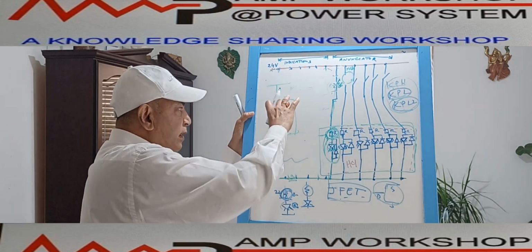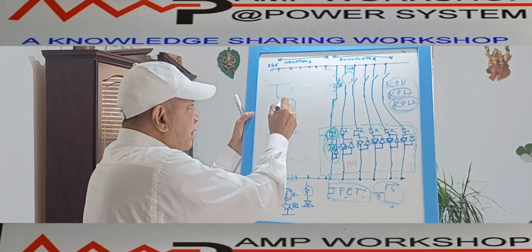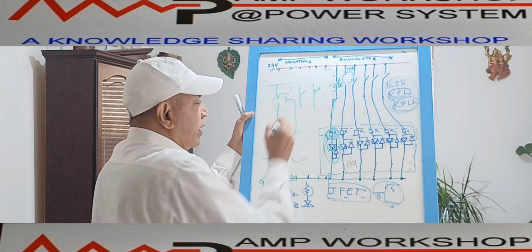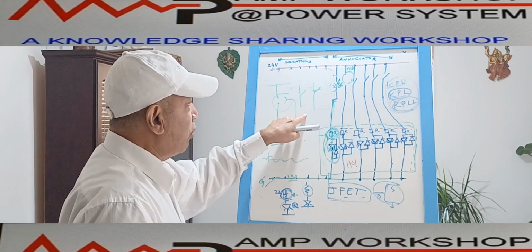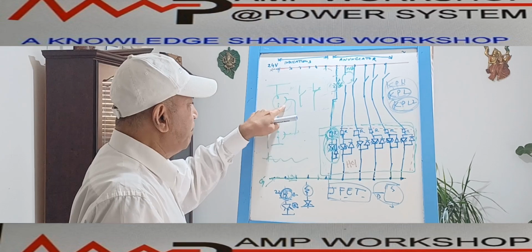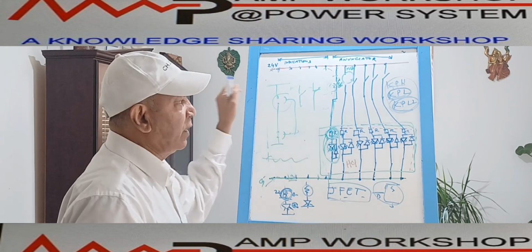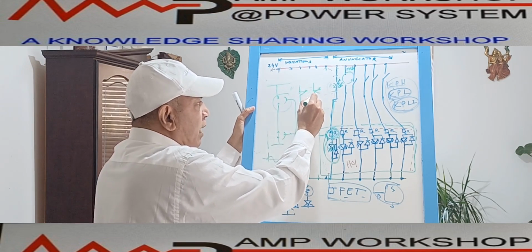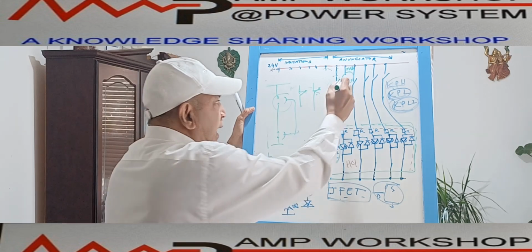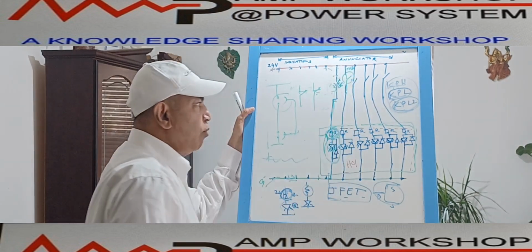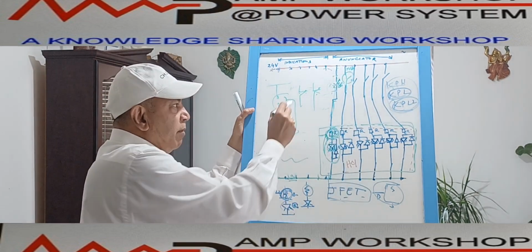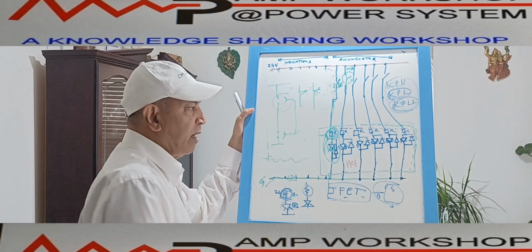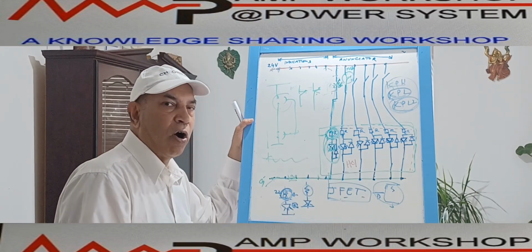So when this MCB gets tripped, this MCB has an auxiliary contact, NO or NC. We can make one NO, one NC contact. This contact is not normally actuated. The moment this MCB trips, it will operate. So the moment the MCB trips, this NO becomes NC and this NC becomes NO. If we use this NO contact over here, the moment this MCB trips, immediately this NO becomes NC, the indication lamp will come on and immediately the horn will sound.